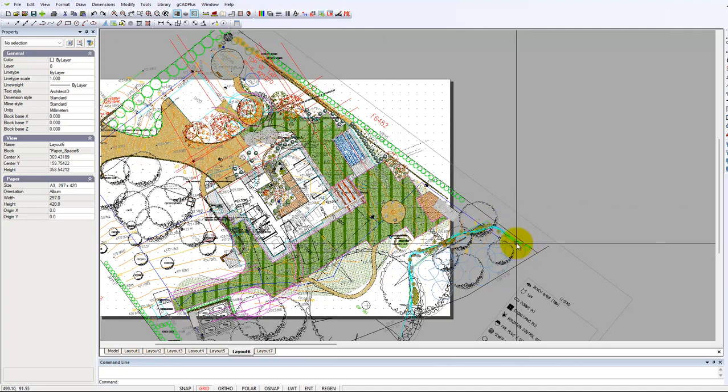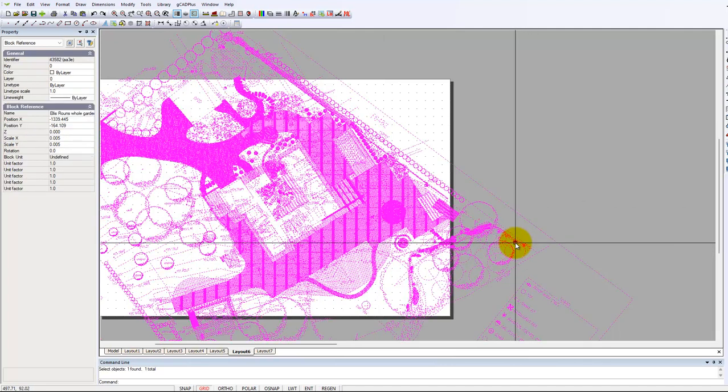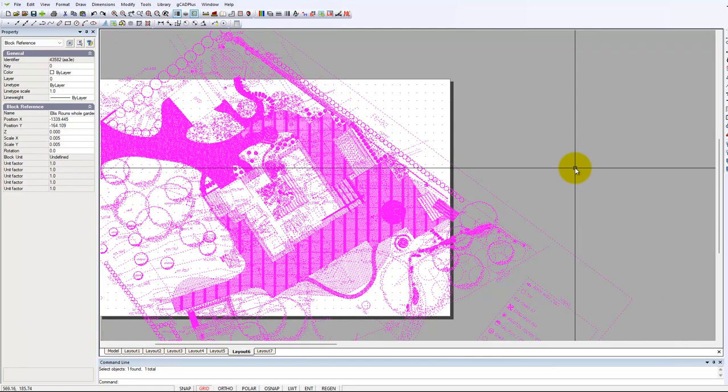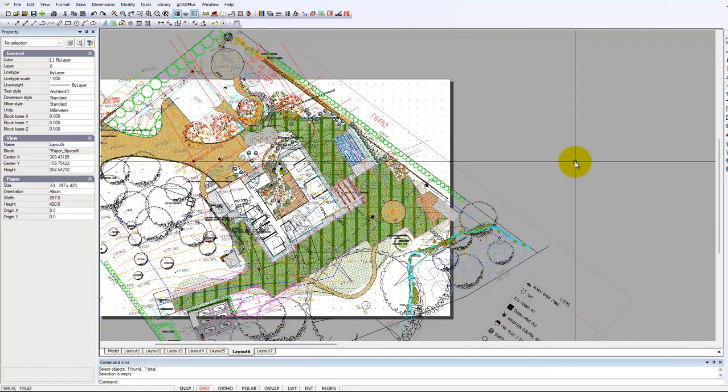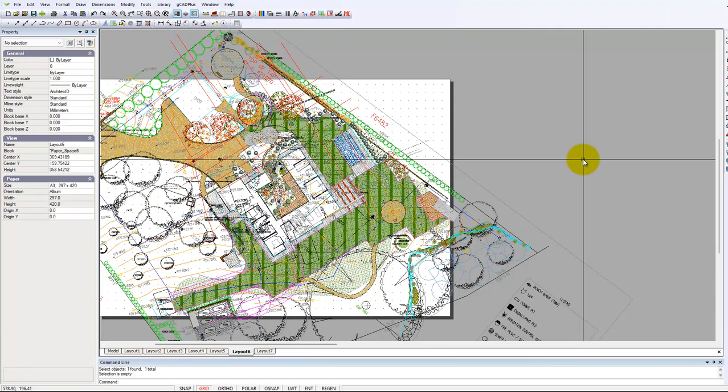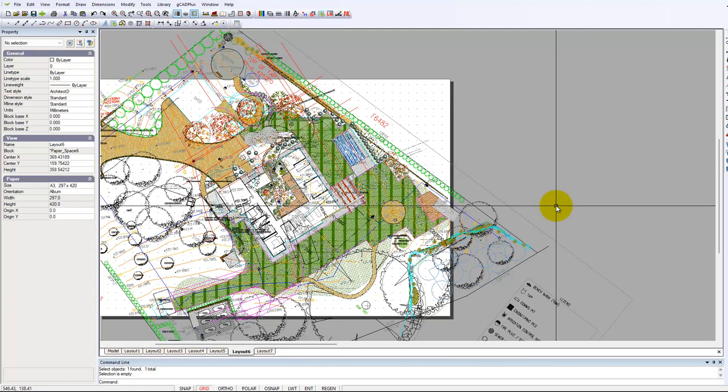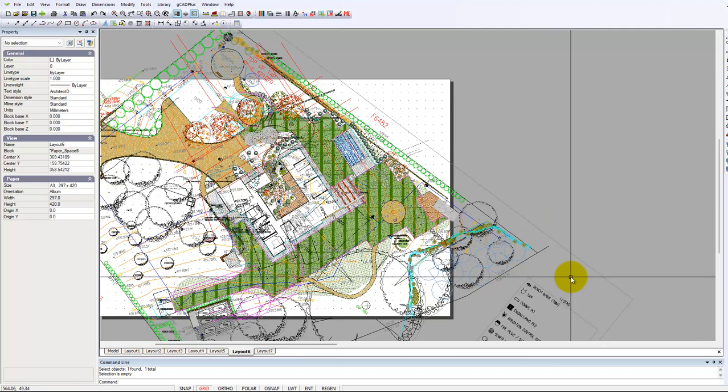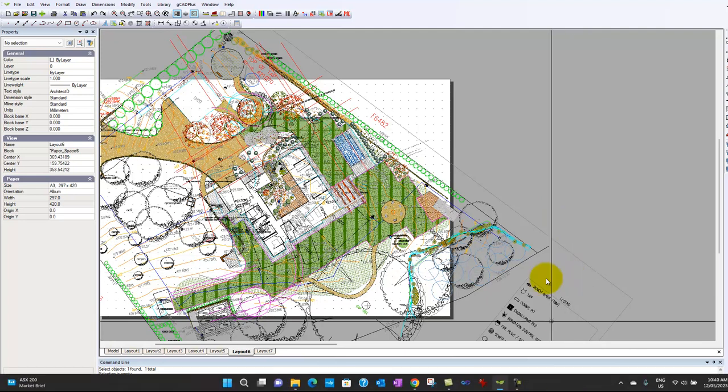Those blocks which are sitting in layout space, lots of them, that one's whole garden, have been copied from the model space environment. So there's endless duplication going on in this drawing. So I'll pause now and get rid of those layouts, because what we're interested in is, can we get in there and design without this drawing giving grief?